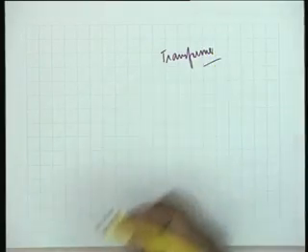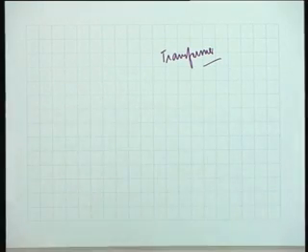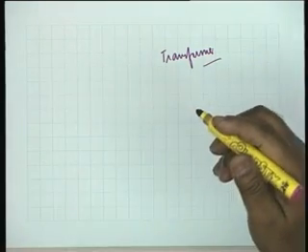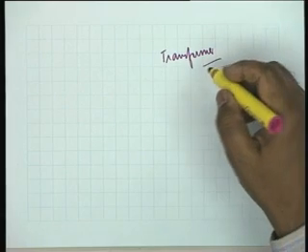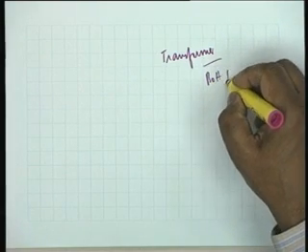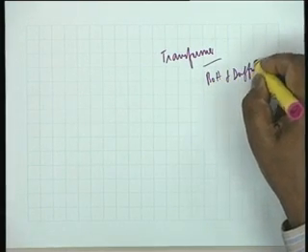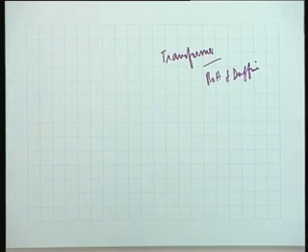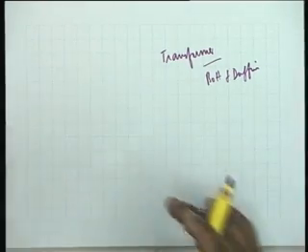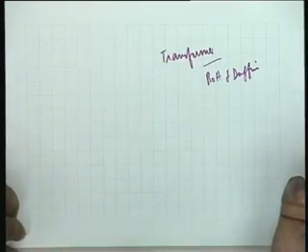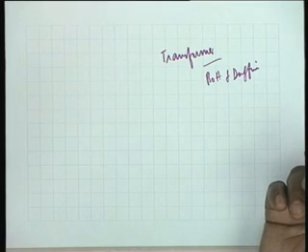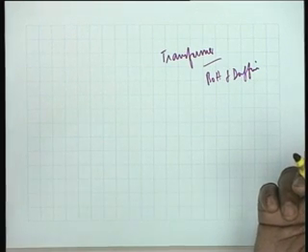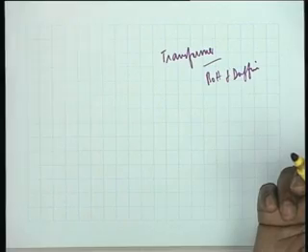If the use of a transformer is allowed, then there is no problem, or you use a non-canonic synthesis of Bott and Duffin or some of its modifications. But as I said, in some special cases, if you are lucky, it is possible to synthesize an RLC impedance function, and we shall take a few examples to check the tricks of the trade. If these tricks work, perfectly all right. If they don't work, then they don't work.